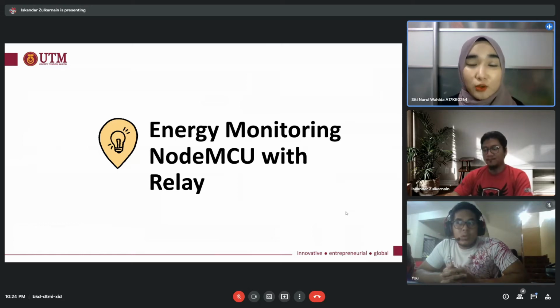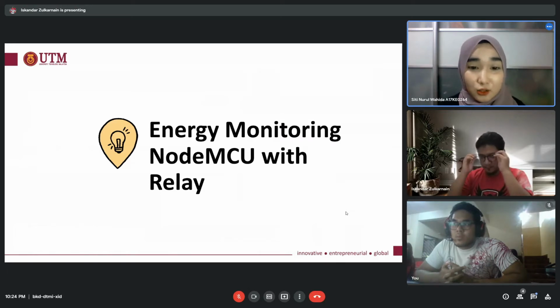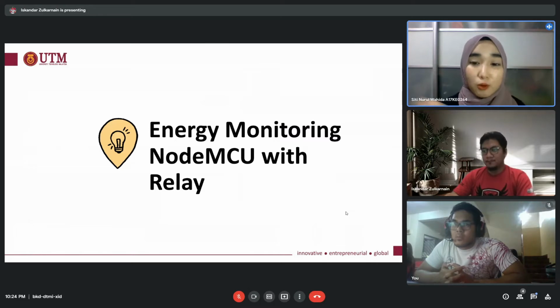This project system works using Arduino with the connection of an ESP8266 Wi-Fi module that will help the user to control the switching off of electrical load in real time using mobile apps. Besides, this system also includes power monitoring using a current sensor to monitor the amount of current and power consumed, and it will be displayed in the mobile apps.